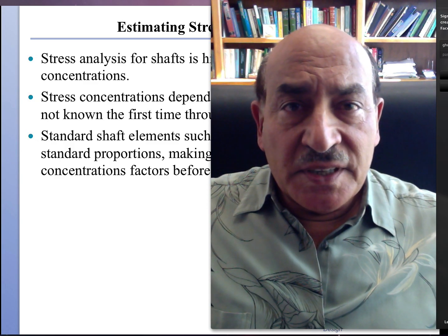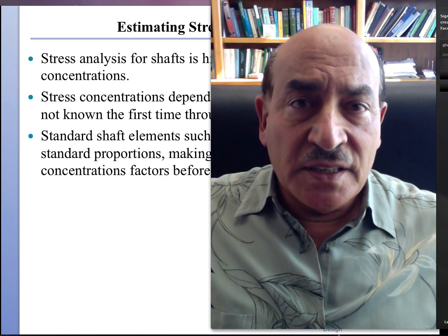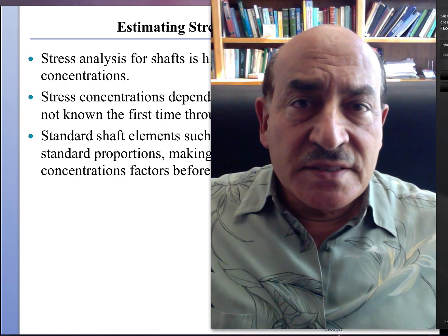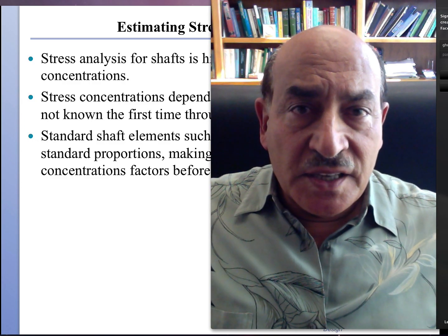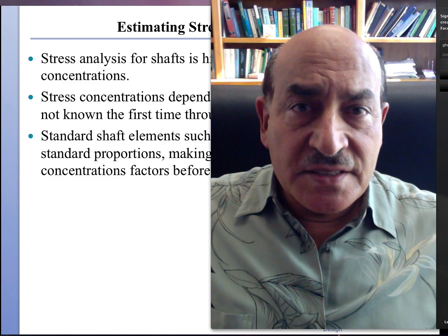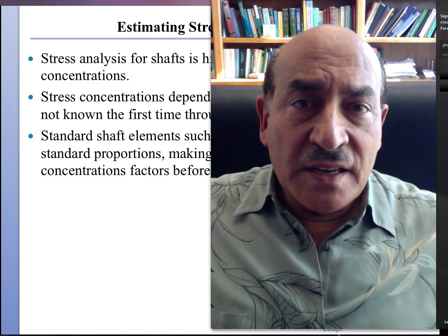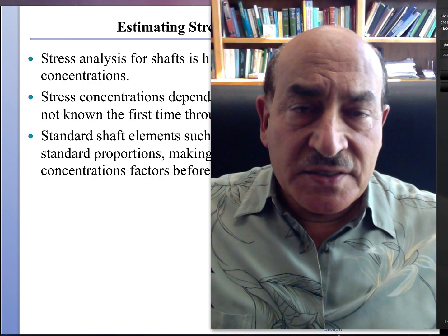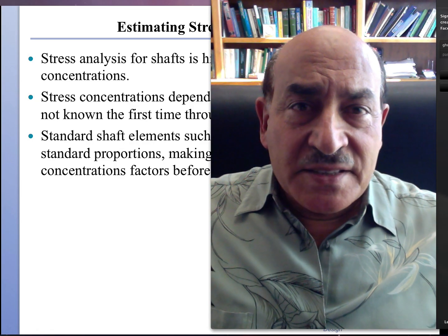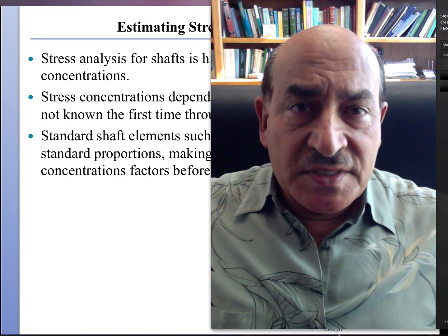If we put the keyway, then that will be under a torsional stress that will also be amplified by the fact that we have to dig into the shaft and generate this groove for the keyway. The same thing also will take place at retaining rings. In other words, the fasteners will play an important role in shaft design, as we will see here.